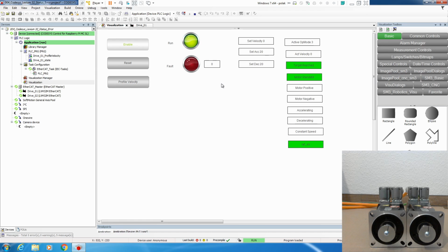I will try it because I have a free shaft, I don't have any load, so technically there is no danger for me. So I unplugged the encoder cable, and we got an error class 4. This error you cannot reset. Let's try. We see that we cannot reset this error. You need a power cycle.